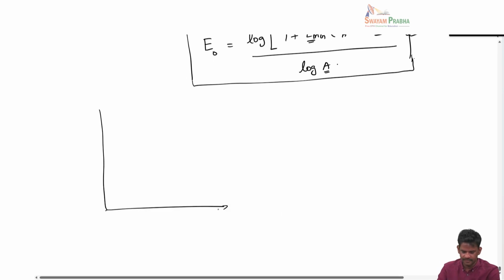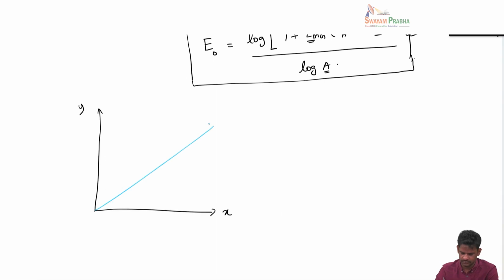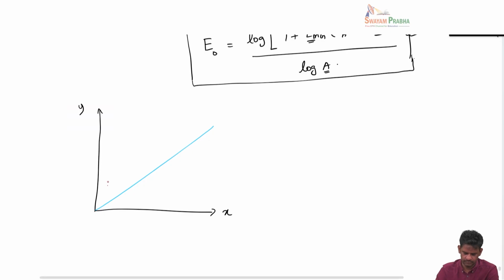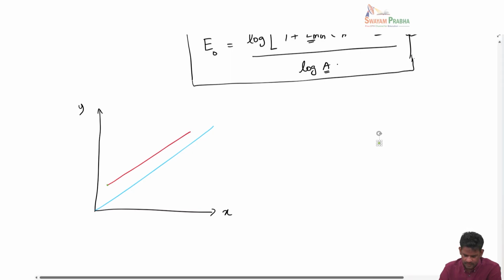Graphically, the way you would calculate the number of theoretical stages or ideal stages is by going horizontally here and then vertical, horizontal, vertical, like this.